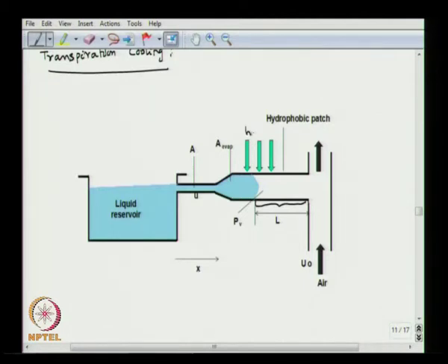So, this is the heat that we apply at the interface, because of which the evaporation occurs, and the air coming in here picks off the vapor and exits, and this process repeats as long as we have an interface there. And as the air carries this vapor, it creates a negative pressure, and the liquid from the reservoir continues to be drawn into the interface.